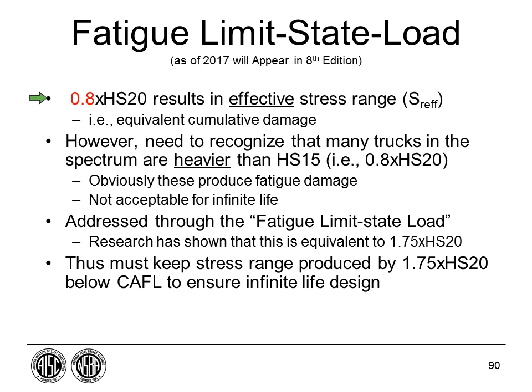Why? Because I know there's many, many vehicles that are heavier than this. That means if I calculated a stress range and I calculated that it was less than a given fatigue limit, and I said, oh, I have infinite life, I'd be wrong because there's a lot of trucks that actually will exceed the fatigue limit, thereby causing fatigue damage.